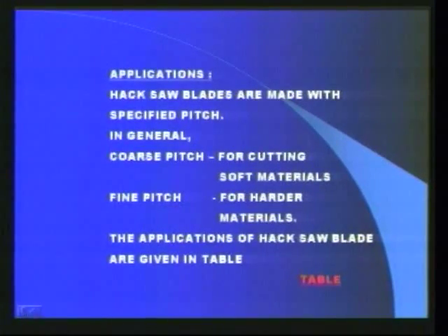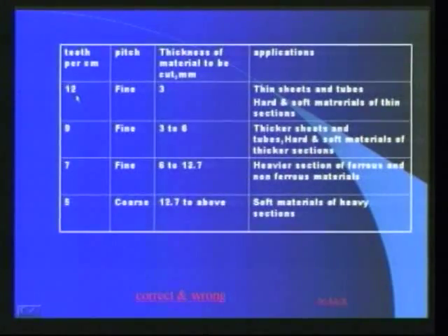The applications of hacksaw blades are given on the following table. If the blade with 12 teeth per cm, it is called fine pitch blade. It can be used to cut material up to 3 mm thickness. This is used for the following applications: thin sheets and tubes, hard and soft materials of thin sections.